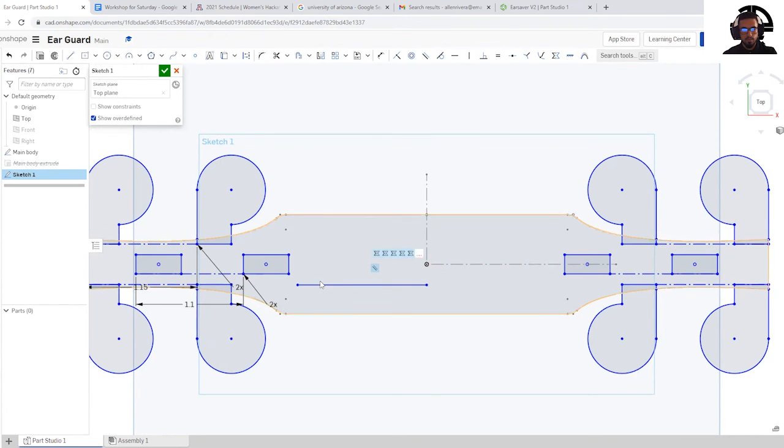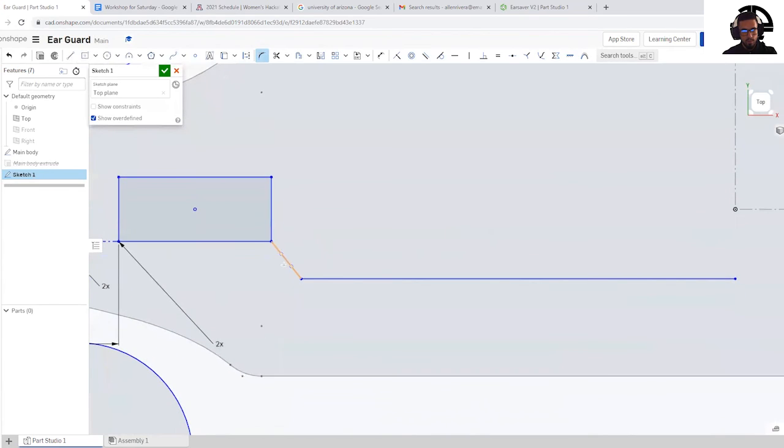So I have a line, and I want it to connect with this line. So I'm going to set a spline right here. It's all good. And I want to have that 0.15 curvature that we set just for design purposes, just so it looks really good. I'm going to click on the spline, click on that point right there, double click on the number, and set it to 0.15, so it's not too exaggerated.